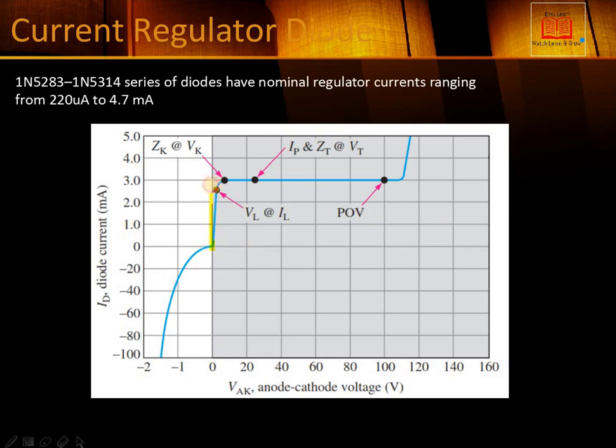This is the constant forward regulated current, and we want to understand it graphically. This is the graph of the forward bias, this region from here towards this side. Please note that this is 0, and here it's 20, 40, increasing by a huge number. For example, one block has a magnitude of 20 lengthwise, while here it's just -1, -2. So this scale is not constant. It is not chosen constant because in reverse bias the current is just slightly negative, it doesn't even touch -2, and it doesn't maintain any constant reverse current.